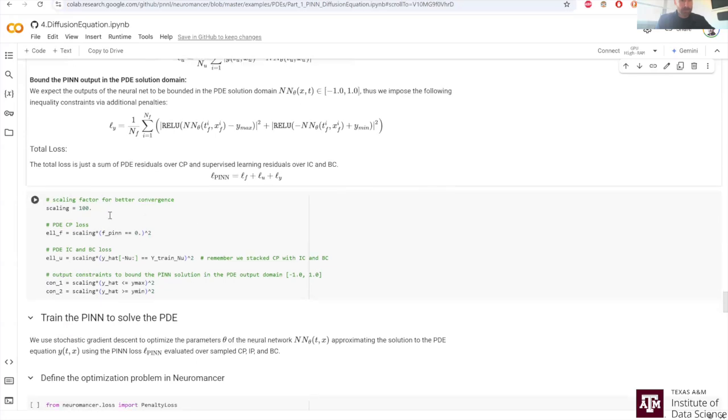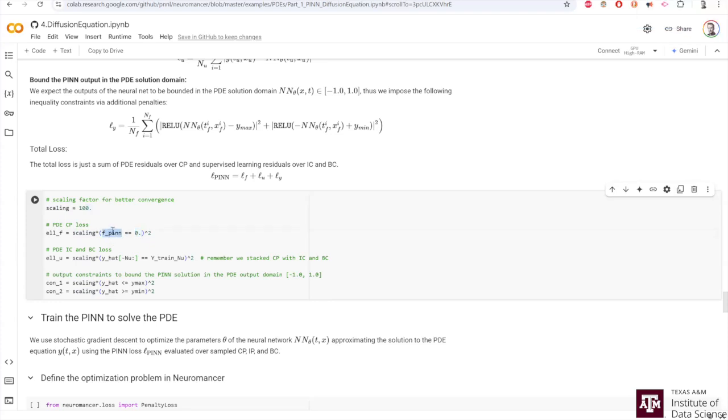And how do you implement that? Well, I provide here the scaling, which is not really important because all of the terms have equal scaling, but in practice you would really need to think carefully about how you balance numerically the different terms in this soft constraint loss function. But what we provide are the automatic constructors for physics-informed loss function terms by operator overload on these comparator operators. So when I have an equal sign, it means that I want to enforce this PINN layer to be equal to 0. And it will broadcast over the distribution of parameters. Yes?